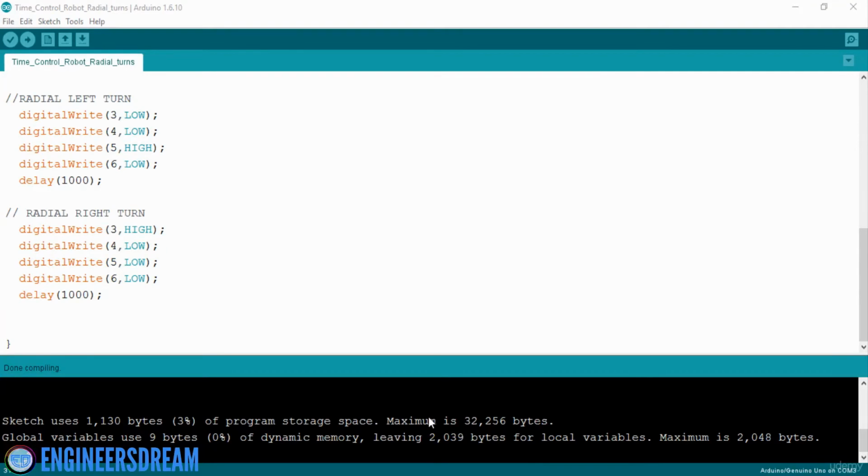Hey, what's up guys, welcome back. In this video, we will write the program for stopping the robot. Now, if we want to stop the robot, then we have to write a condition of high on all the 4 pins, or we have to write a condition of low on all the 4 pins.